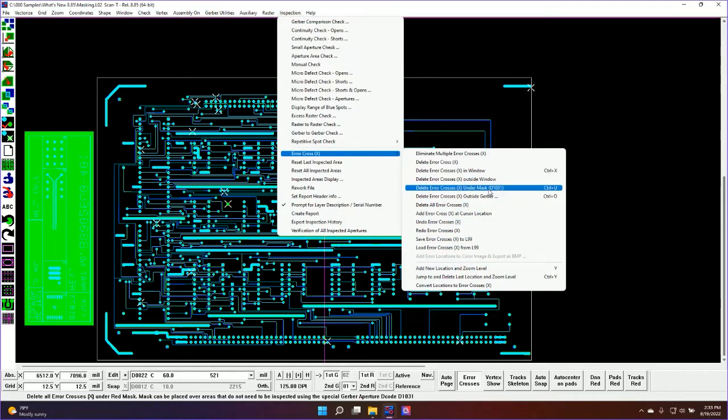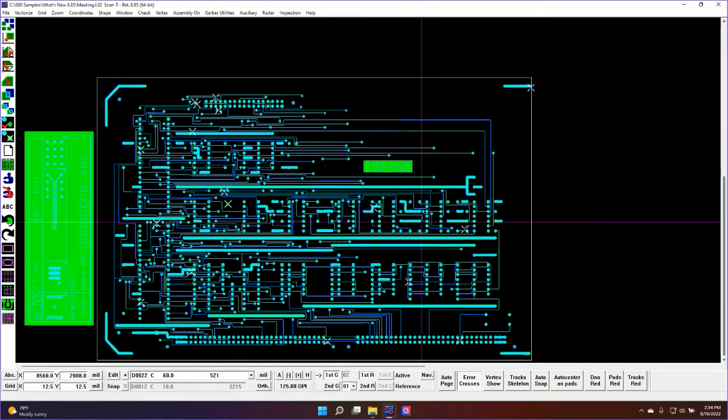And what it's going to do is it's going to use a specific decode on your active layer. So we're going to dive in a separate masking video. We'll talk about how to create the mask. Very, very easy. But basically what you're going to do is on your inspection layer with your inspection Gerber data, you are going to create shapes made out of a specific Gerber shape, Gerber aperture. And all those shapes will be masked. And again, we'll cover that in a separate video. Very, very easy to do.